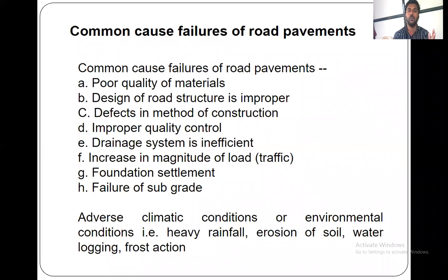Along with these parameters, there are also certain parameters like adverse climatic or environmental conditions. That is, heavy rainfall, erosion of the soil, waterlogging condition, frost action. If such environmental conditions occur, the road will get failed because while designing we have not considered the heavy rainfall and erosion of the soil.